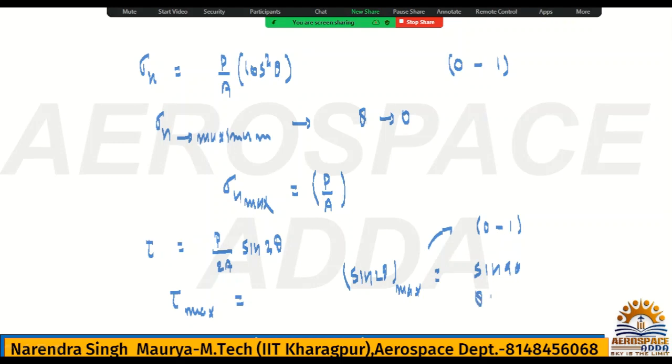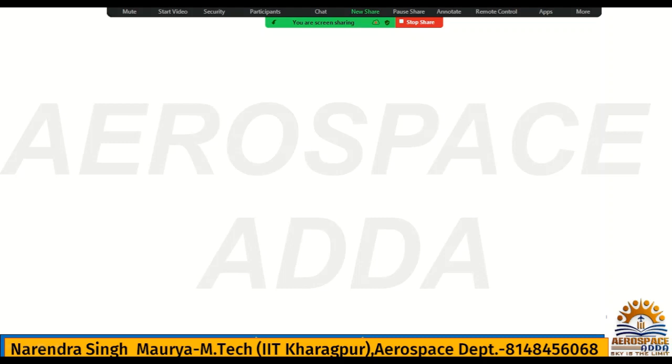So what will theta be here? 2 theta is equal to 90, so theta is nothing but 45. Exactly at 45 degree, you will achieve that tau max. Okay. So tau max you will achieve when theta is 45. That is for 1 mark aptitude questions, that you need to remember. And what will be the value? The value will be P by 2A sin 2 theta, where theta is 45, sin 90. That means tau max is nothing but P divided by 2A.